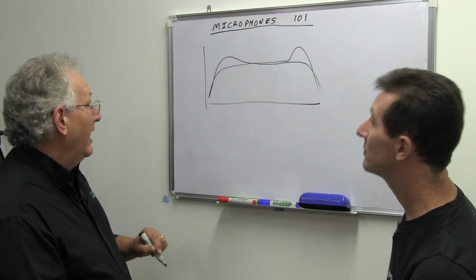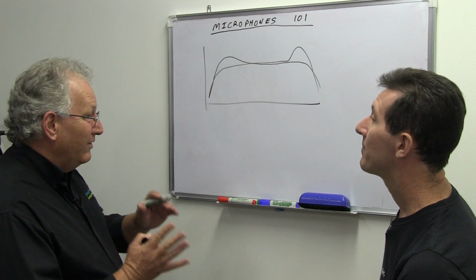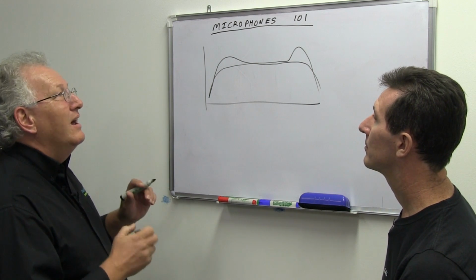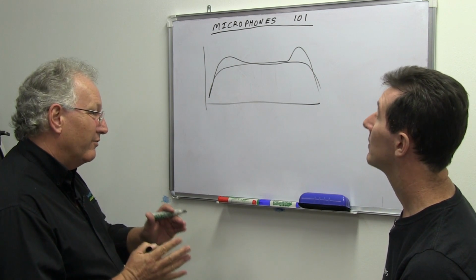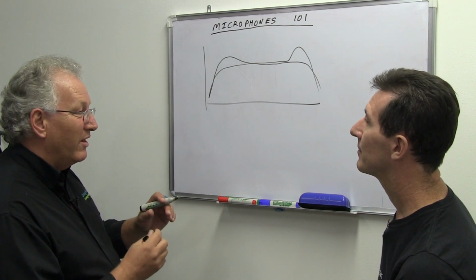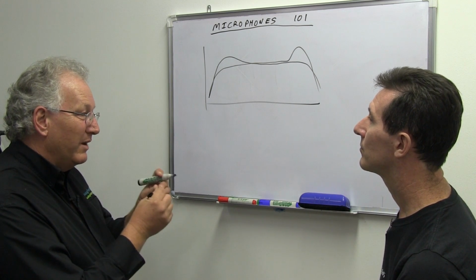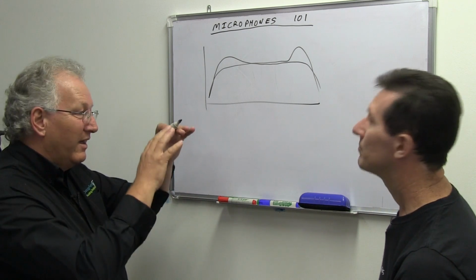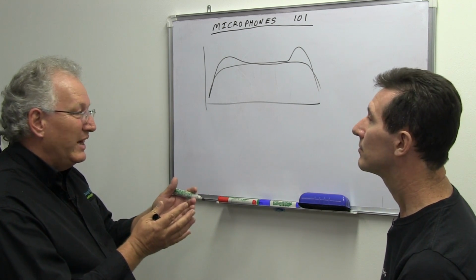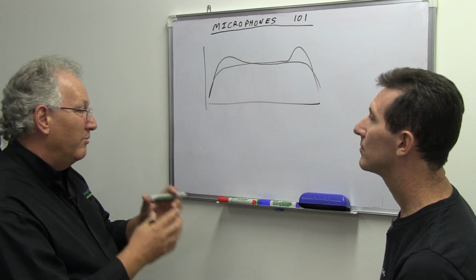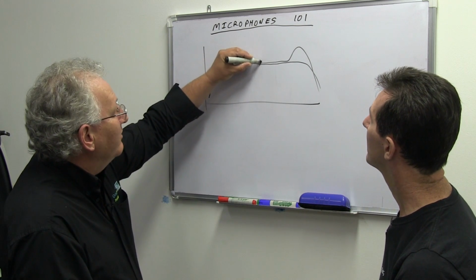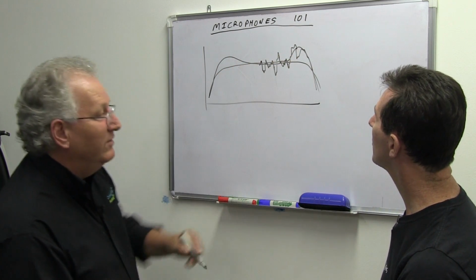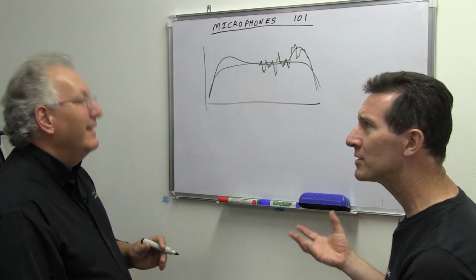Of course, yes. So the frequency response is one thing, but that's the coarse frequency response. You also get microstructure to the frequency response, which is shaped by the fact that the microphone pickup element is surrounded by stuff: the supports, whatever kind of mesh housing it's got, the microphone body itself, all of which adds very small deviations, which are mechanical resonant type effects.